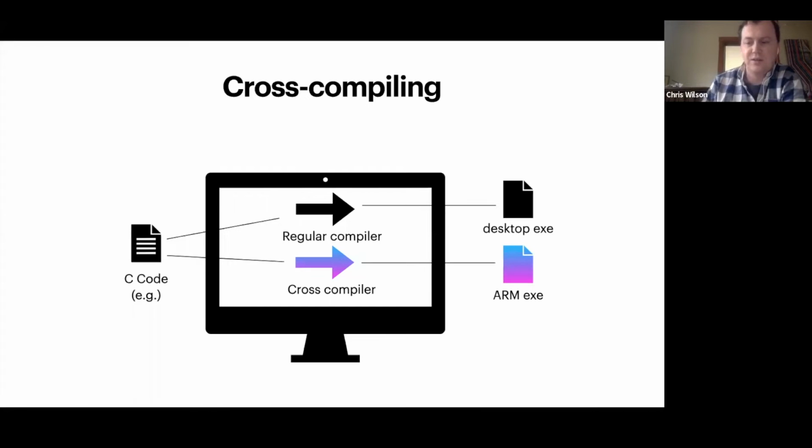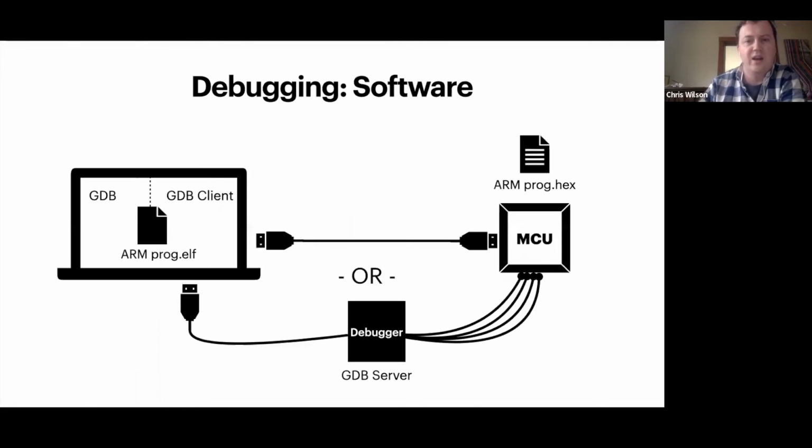And so then once you've compiled your program, you have to get it onto this external chip. There are various ways to do it. The one that I was working with happened to have USB, so the IDE could directly copy the compiled program over a USB connection and put it onto the chip.